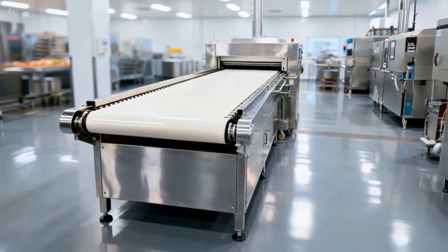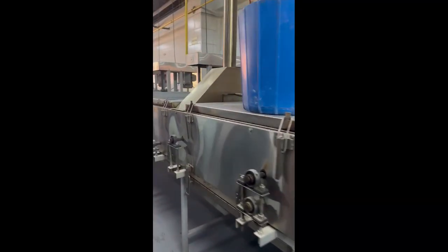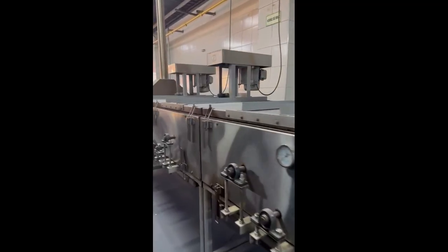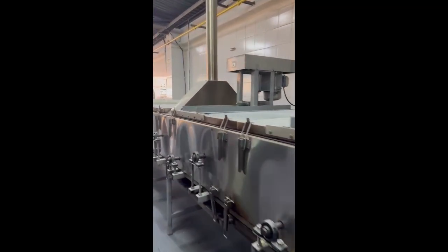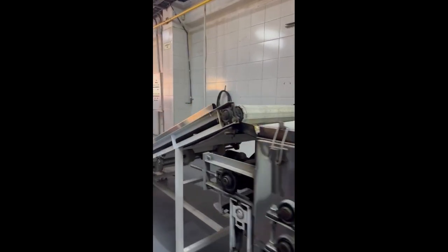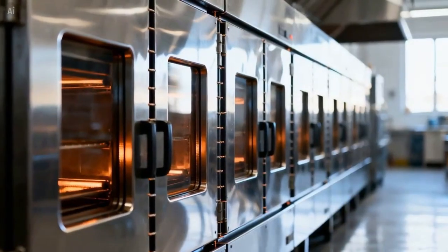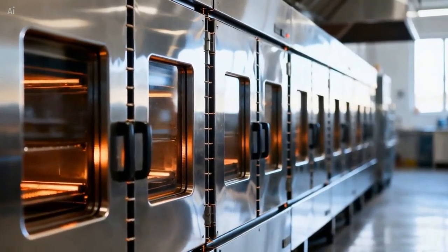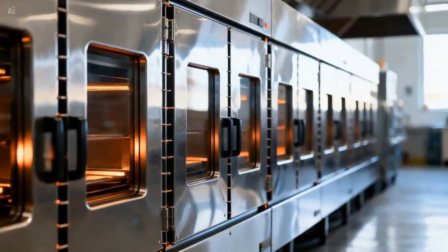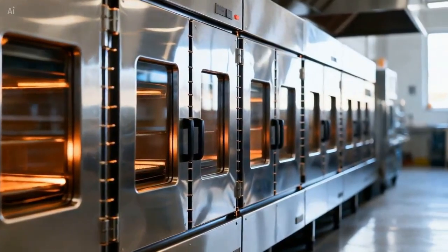Let's take a look at our case study, the continuous belt dryer for corn shown in this file photo. It features an outer frame made of AISI 304 stainless steel, chosen for its high corrosion resistance and ease of cleaning. The design is modular, allowing for the configuration of a zone temperature profile along the entire path for the various stages of dehydration and roasting.